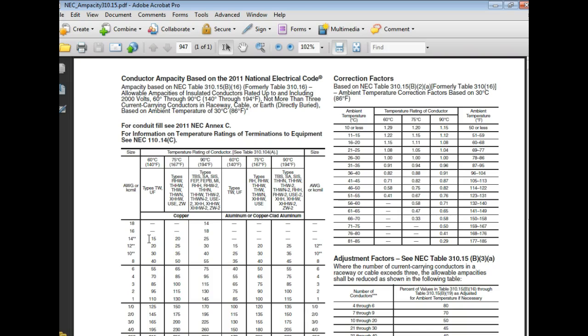It has a real high coefficient of expansion and contraction. So that means with temperature it changes a lot. So you really have to crimp these things down, because over time, if you run it in a wide temperature change, they're going to work themselves loose, right? Another problem we have is the oxidation rate for aluminum is extremely fast.